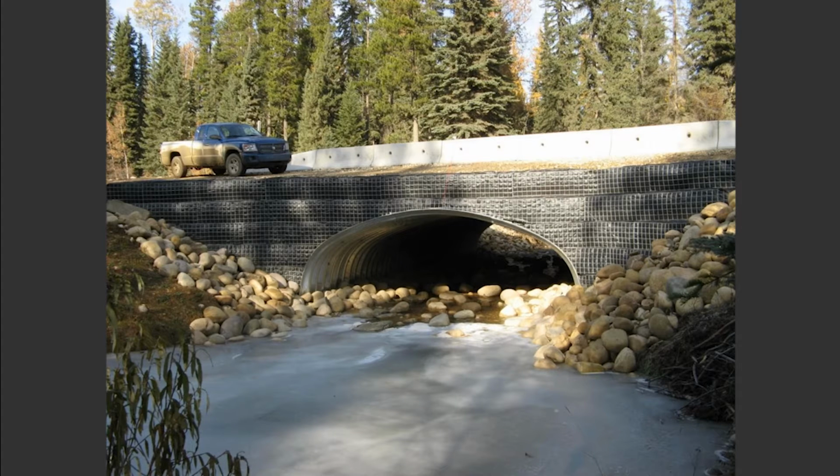It also has a very complementary installation method with structural plate products. Both require engineered, well-graded backfill. Both require compaction of that material to 95% standard Proctor density in roughly 8-inch lifts. So, when it comes to construction costs, it's typically not a huge cost adder when we're talking about these types of MSE walls used in conjunction with a bridge plate arch, for example, as shown here.